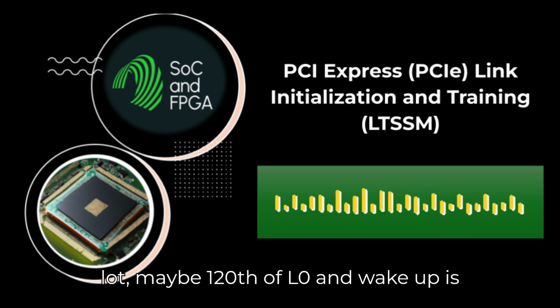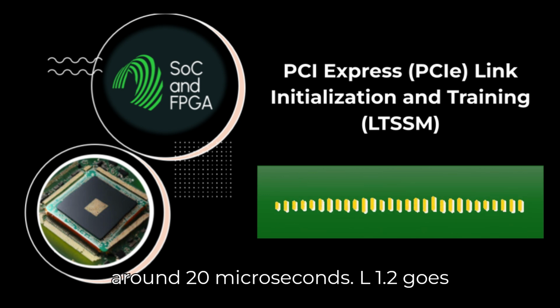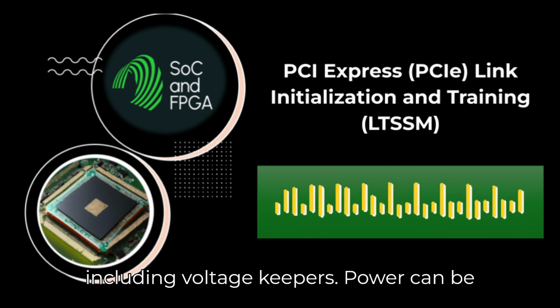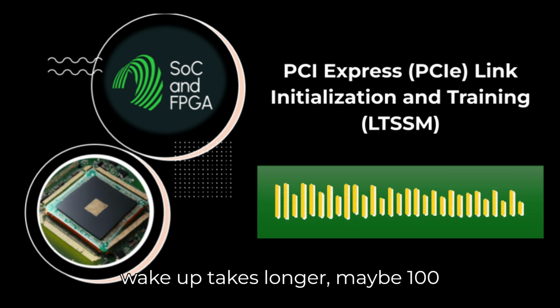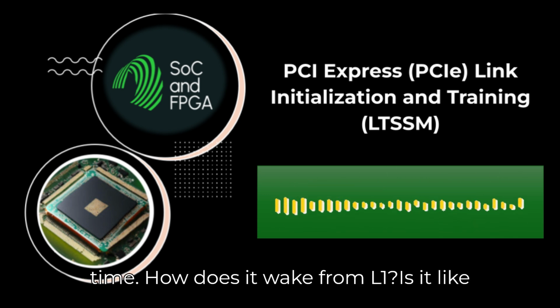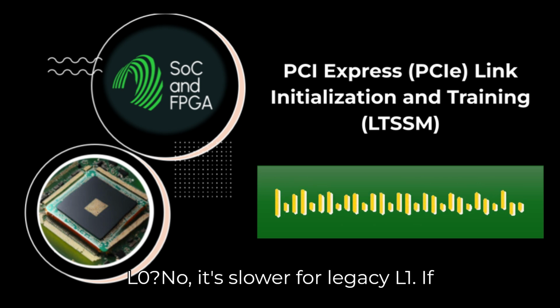Power drops a lot, maybe 1/20th of L0, and wake-up is around 20 microseconds. L1.2 goes further, everything high-speed is off, including voltage keepers. Power can be incredibly low, tens of microwatts, but wake-up takes longer, maybe 100 microseconds. Okay, power versus wake-up time. How about waking from L1? Is it like L0s? No, it's slower.